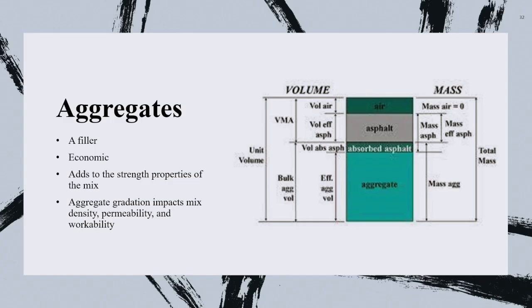But yeah, again, talking about concrete, you're talking about cement, water, sand, gravel, and voids. Soils, you're talking about solids, which could be gravel, sand, silt, and clay lumped together, then water, and then air, right? The addition of the three, the solids, that's what your soil is made of, right? A mix of gravel, sand, silt, and clay, the 4 main constituents. There could be some organic matter, but then plus water if you're under the underground water table, plus some air voids.